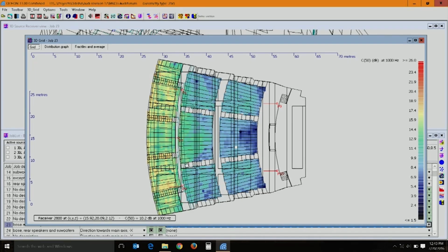This actually becomes a double space where the absorption conditions in this zone are different because the volume is different, plus the one below the balcony the volume is pretty less, the absorptions are different. So, the clarity is higher. It does not mean this is good, it is also not preferable that there is a stark difference between a row here and the next row here, the clarity is kind of distinctly different.